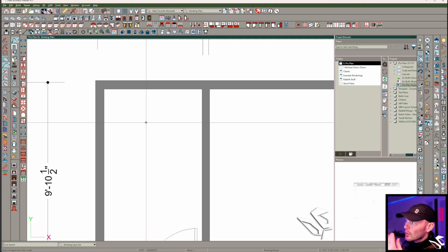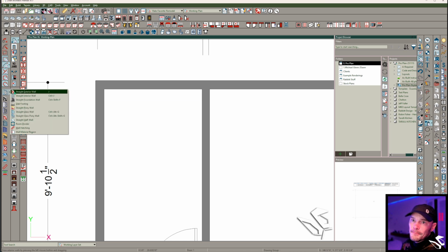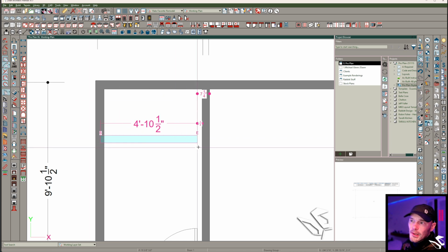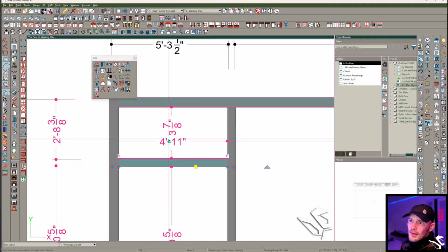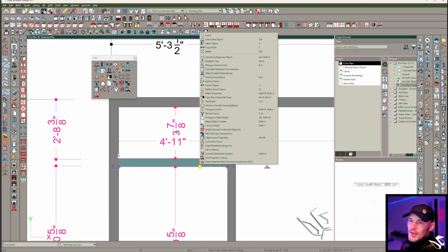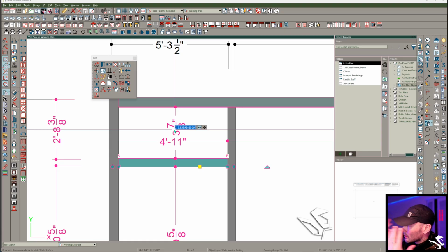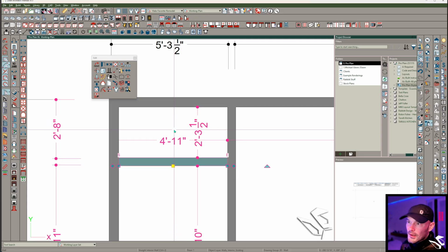And so a really simple configuration might be that we use what becomes a pony wall to create a curb. And so the inside dimension of this is one thing. It's really the outside dimension that I'd want to know about, right? And let me just do some math in my head. I'm using a 4.5-inch interior wall, so I could say that I want this to be 32 minus 4.5. All right, and so that's going to be my overall shower.